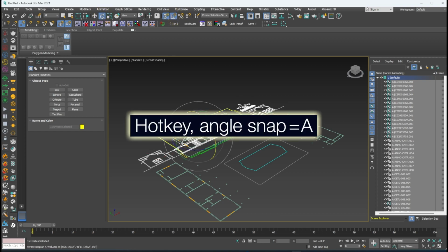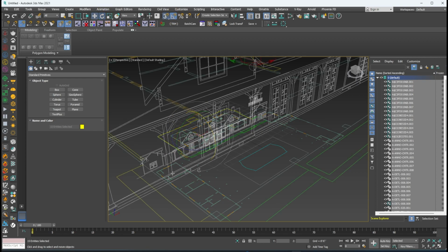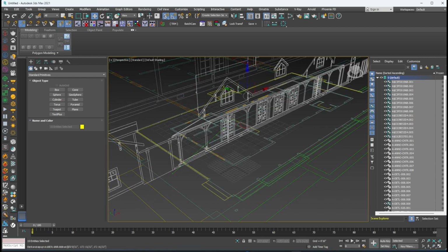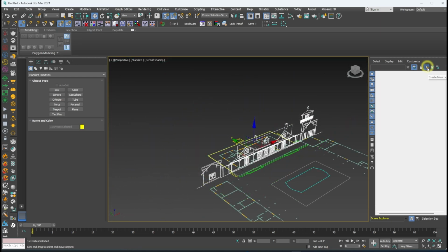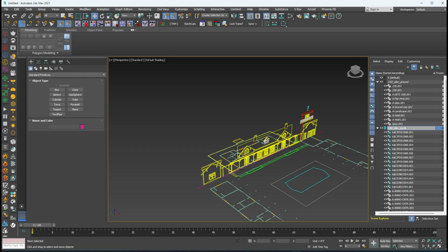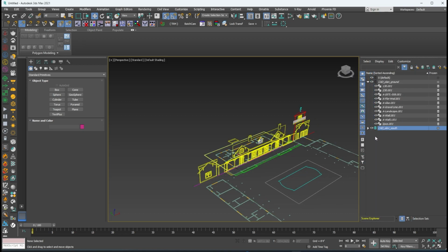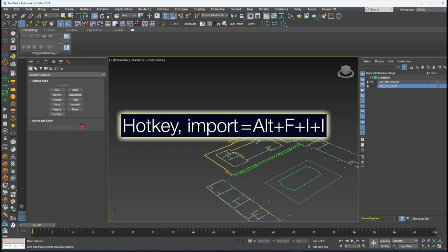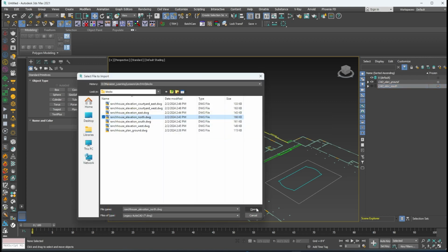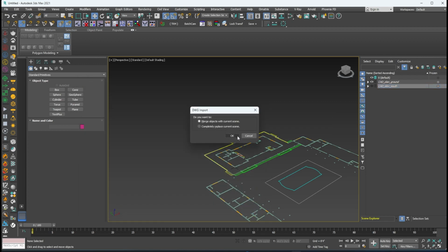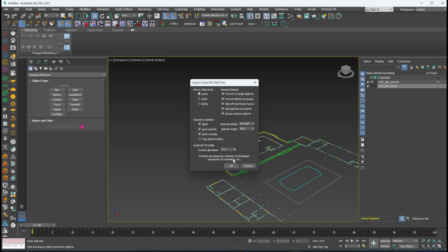You will need to rotate and position the elevation drawings so they correspond with the plan and with each other, creating a separate layer for each one. Remember that Legacy AutoCAD import places everything on the active layer, so make sure to activate Layer 0 after completing each import. Hide each elevation layer before importing the next one. With practice, this process typically takes about an hour.